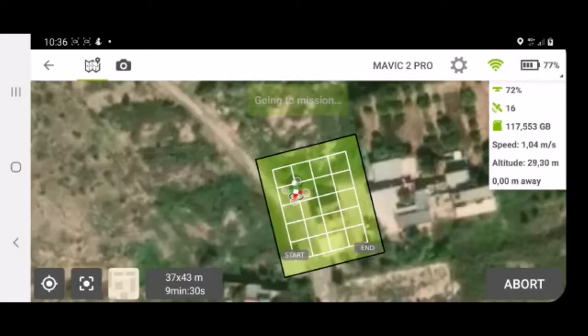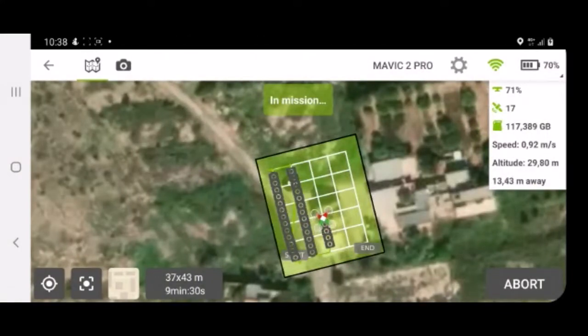As shown in the panel, the altitude will continue to rise until it reaches 30 meters. Once the designated altitude is reached, the drone moves to the mission start position. Once the flight mission has started, we must visually monitor the aircraft and at the same time keep an eye on the panel of our terminal connected to the controller. We observe relevant information such as mission duration, drone location, speed or altitude. The number of connected satellites is 17, on which it depends to geolocate the drone and fly more accurately.